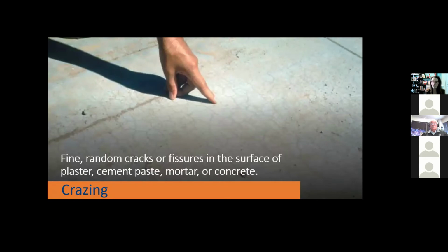Same issue we can get with plastic shrinkage cracking. So you often can see crazing and plastic shrinkage cracking in the same slab. This can happen in vertical concrete and in horizontal concrete, and you have to have good eyesight, which mine is changing depending on distance. But without my glasses on, I probably don't see a lot of crazed concrete, but put them on and there they are, especially after it's going to soak into the surface cracks. These are just at the surface, so it's a fine network, typically tight cracks.